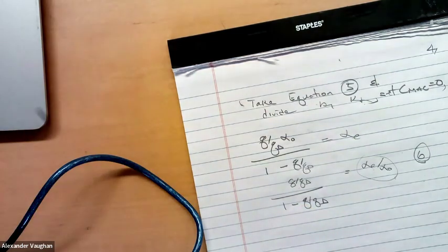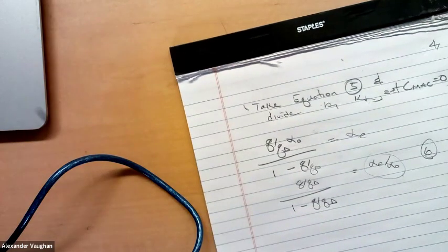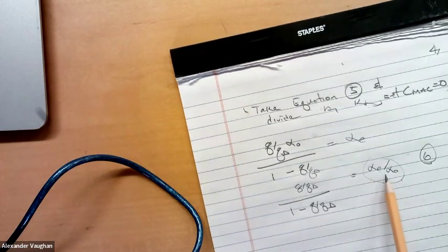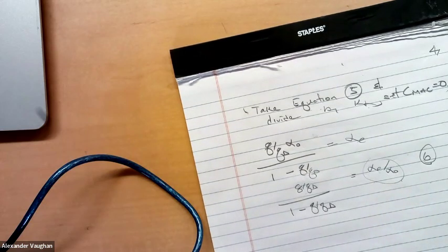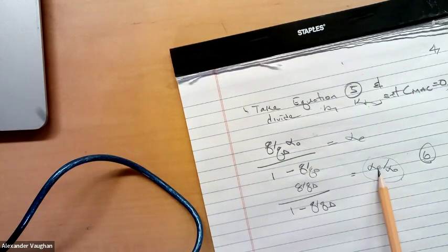Okay. Now, there's another thing you can do, and I was talking to a student about this the other day. Another way to look at it is you could take this equation and you could either do it computationally, or let's talk about the experiment first. If I were in the wind tunnel and I was not yet at the divergence Q, I'm below the divergence Q, I could measure alpha E, and then I could solve for Q divergence at that particular Q. You with me on that? No. So let's do that.